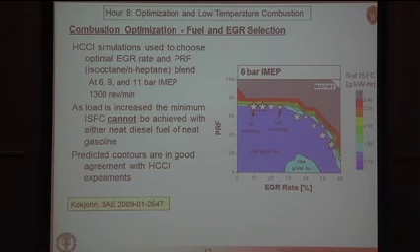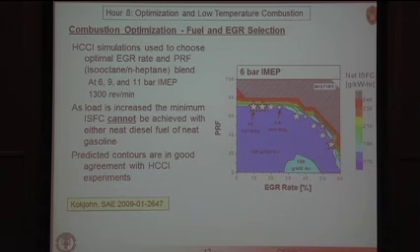This is homogeneous charge compression ignition. And what we plotted here is the indicated specific fuel consumption. Basically, you'd like to operate in regions that are nice and blue here for low fuel consumption. Red is poor fuel consumption, and if you go beyond that, you actually misfire. You don't get combustion. The other interesting thing is the stars. The smaller the star, the smaller the pressure rise rate.